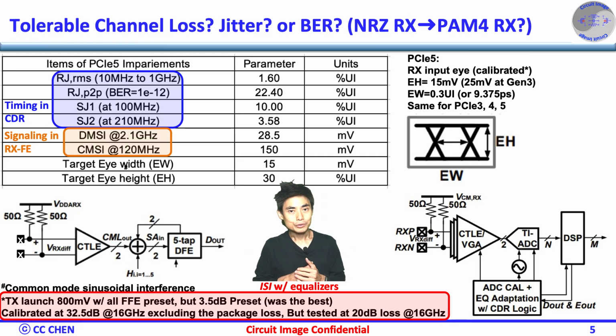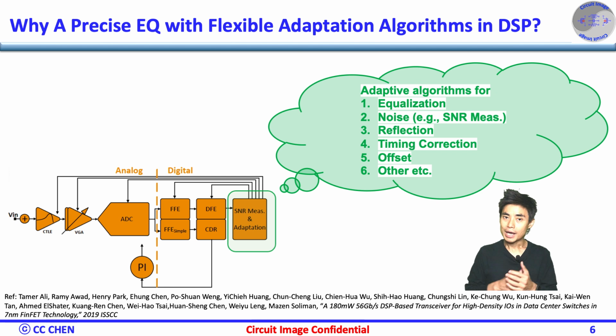From the equalization point of view, we need to address here. If we are able to convert the analog signals to the digital with a much lower quantization noise error, we could then use the digital data to represent the analog data precisely. Then the DSP will apply those digital data along with the complicated adaptive equalization algorithms to reduce the ISI effectively and precisely in different environments. In addition, the DSP using these techniques can adaptively compensate for channel distortion and optimize the RX intrinsic performance, making the system more tolerable to changing channel conditions.